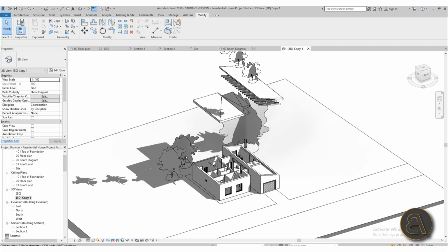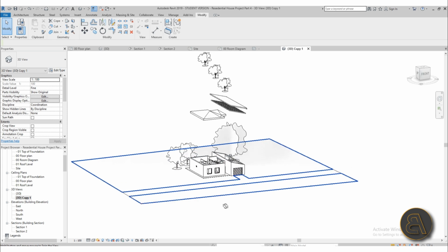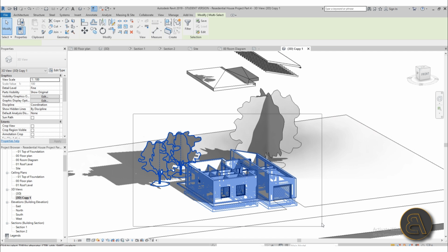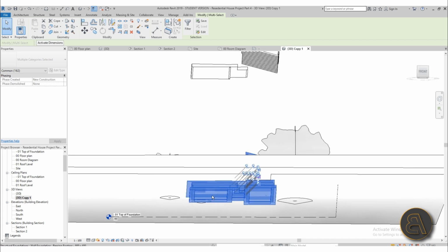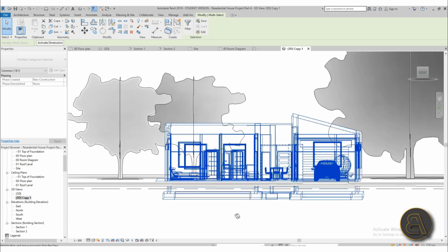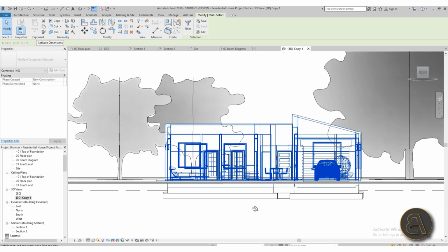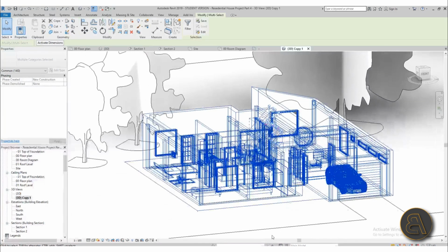Now the actual house is the hardest part because we want to reveal the foundation too, so we need to lift up the house. And the easiest way that I found so far is to just do a whole selection, select everything, orbit around, and then by just holding the shift key, remove elements from selection. So we basically just need to remove the whole foundation like this, maybe orbit around, just do clever orbiting, and then let's try to remove like this. So just all of the foundation walls and the whole foundation, and the rest should stay selected.